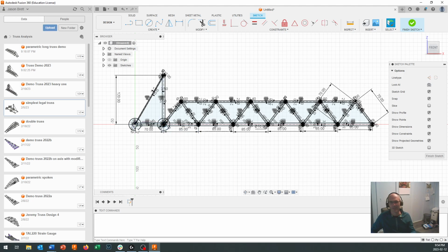This lever arm's really short here, which is probably going to cost me. That's going to make the total amount of force coming up in here pretty darn high. And so I might be wiser to shorten some of this down and make this a little bit longer, but we'll have to see. Simulation and testing will let me know how I am doing on here.